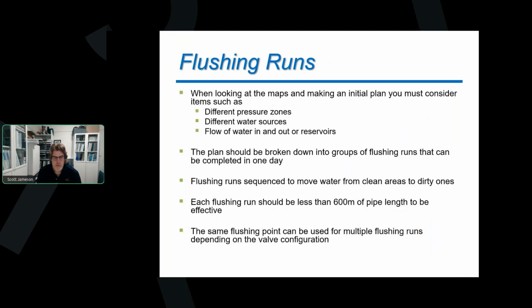Now, when we're also at our desk looking at those initial plans we're going to make, we need to look: are there different pressure zones in my system? If there are, then we're going to flush one pressure zone completely and then move to the next pressure zone and flush that one completely.